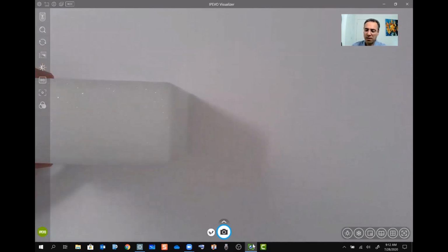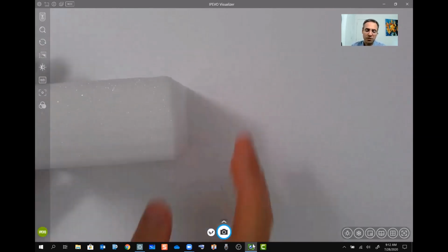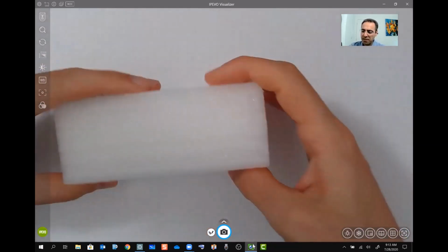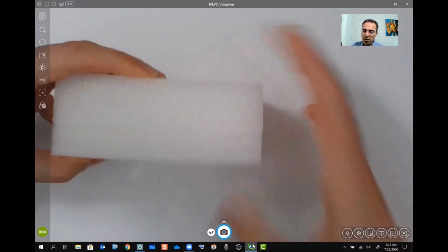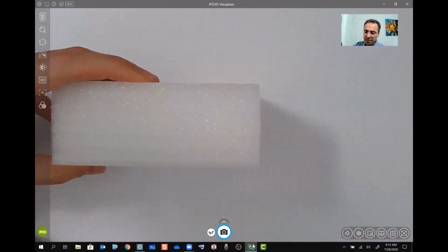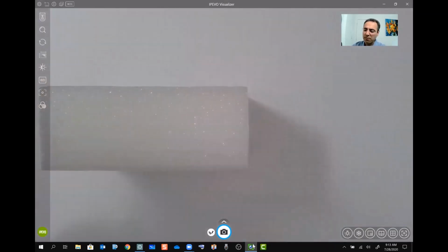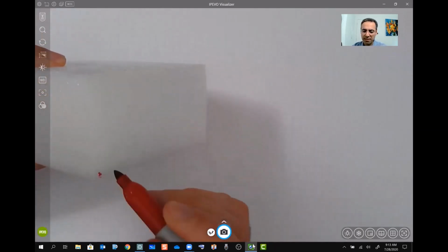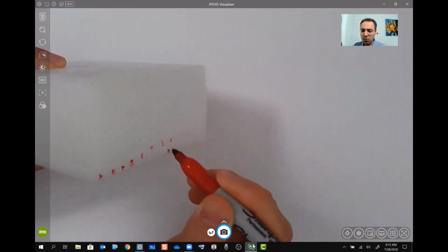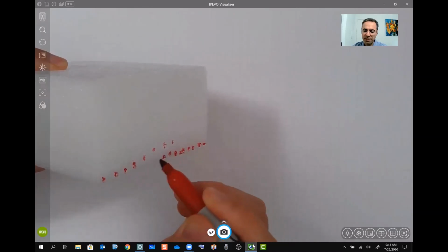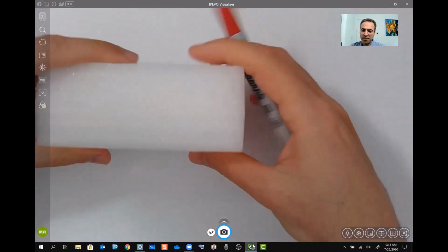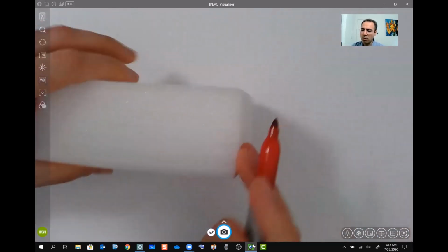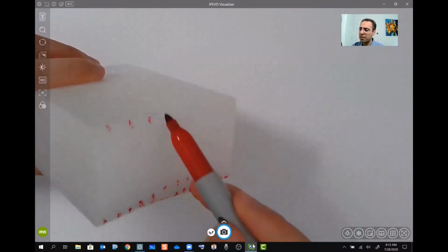And now I said, imagine we cut that beam and we're just looking at a section of that beam. All right, this is a section of that beam. The same thing, we try to bend it, that's a small section. The bottom is under tension and the top is under compression. Now, if I look at the cross section of this beam, all the points here at the bottom are going to be under tension. Remember, I will bend it like that. The bottom is under tension, and all the points at the top are going to be under compression.